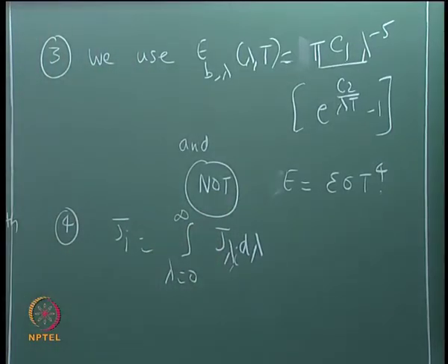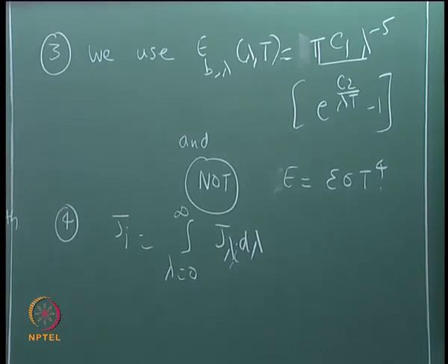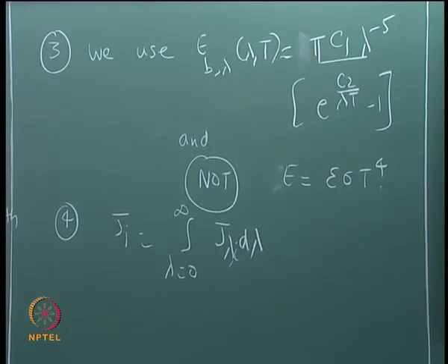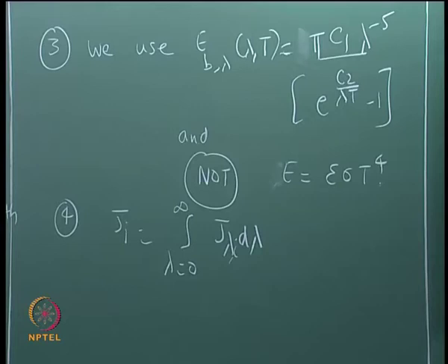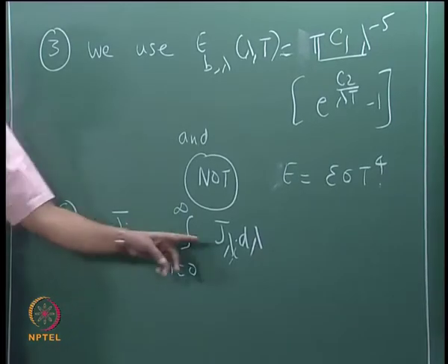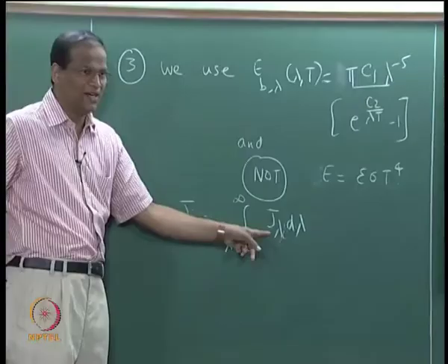If you don't like J lambda i, you can use J i lambda, it does not matter. Lambda and i must come, lambda is spectral and i is the ith surface. We just want to leave it as J lambda because we are talking about radiation heat transfer in an n surface enclosure. So this makes it the spectral radiosity formulation.